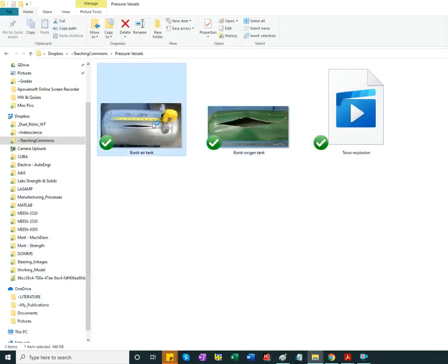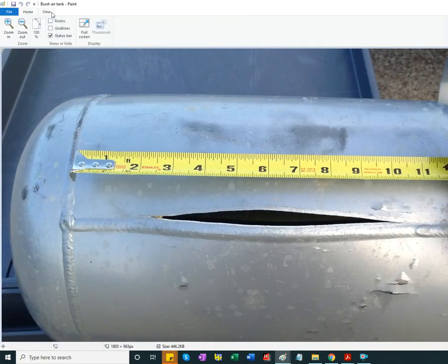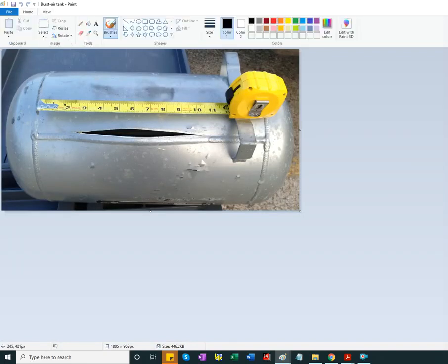This other one shows us two things. It shows us that again the hoop stress is bigger than the longitudinal stress. It could have instead, if they were equal but they are not, could have burst next to the weldment, either here or on the other hand. So I said two things to observe here: that the hoop stress is bigger than the longitudinal stress in a